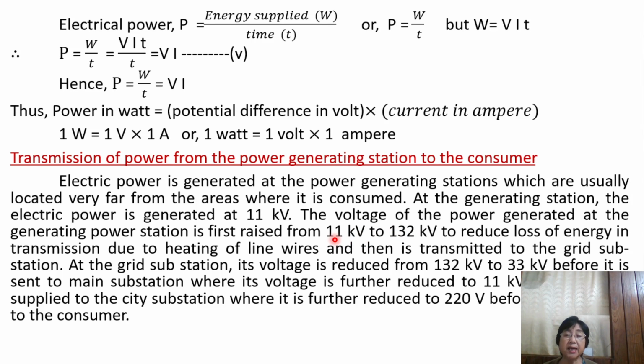So it will be raised 12 times high. And why is it raised? The reason is this: to reduce loss of energy in transmission due to heating of line wires.